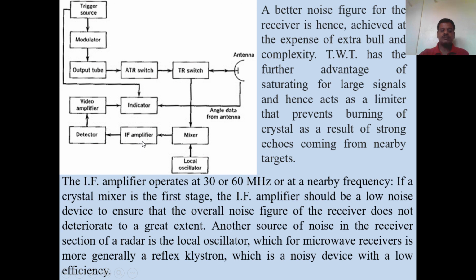If the crystal mixer is the first stage, then the IF amplifier should be a low noise device, and it ensures that the overall noise figure of the receiver does not deteriorate to a great extent.